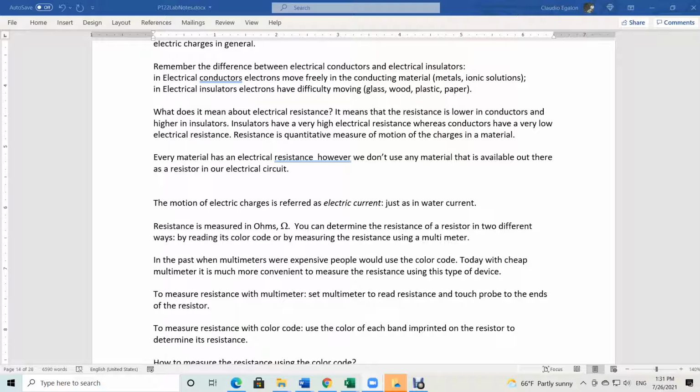But if I go to the most sensitive scale that I have, we see that it displays not 0, but something still small, 0.6 ohms. Okay? And now I can start measuring the resistance of my hand, for instance. That's a nice exercise that we do in the lab.